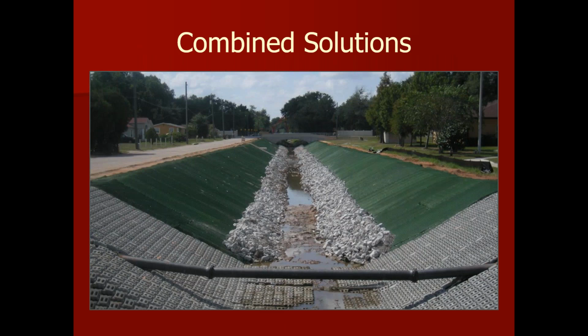There's never one tool in our box that's really suited for everything. So the trick is to be able to pick the proper tool. You can see we have ACBs in an area right downstream of an outlet rock where the ordinary high water would come up to, and then a TRM on the side slope of this channel to be able to provide vegetated protection in conjunction with the other components of this system that were developed to provide stability in this area.